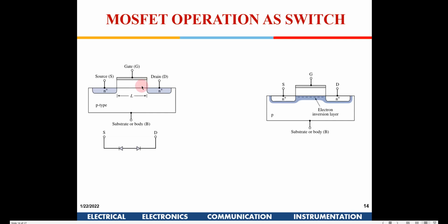It depends on the dielectric used and the thickness of the gate oxide. Every technology defines the maximum that can be applied so that the dielectric doesn't break. If you give high voltage, the dielectric will break, electrons will tunnel through, and then your device will break. So you can't afford to give voltage beyond the specified limits.